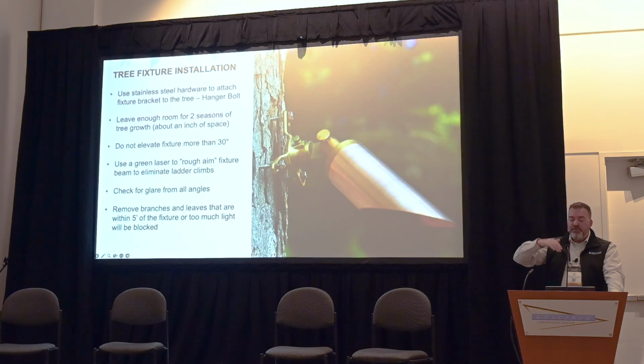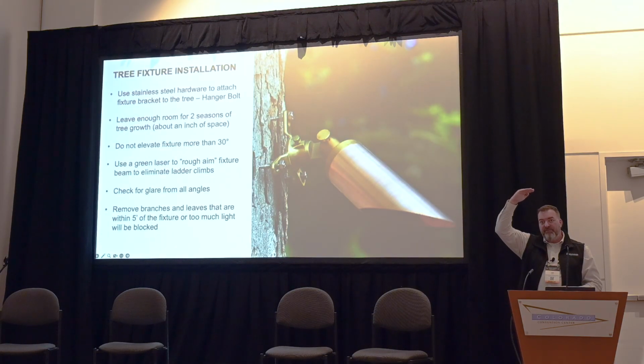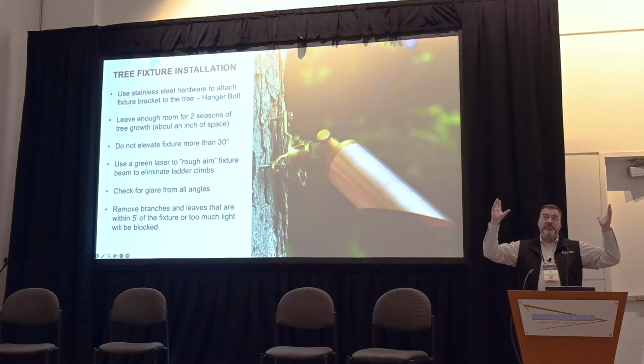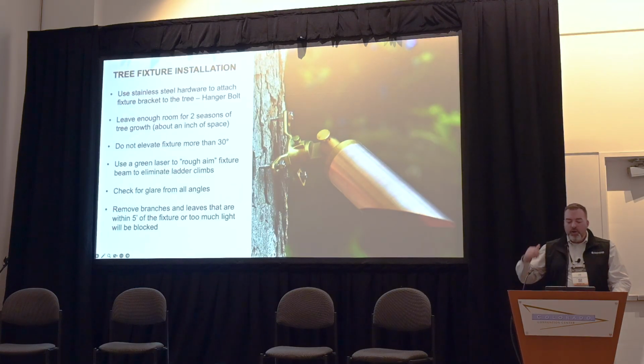But for downlighting, I try to keep it up about 30 feet, because if you look at our peripheral vision for where we see, about 25 feet above our peripheral vision, it kind of fades off. So if you can get that tree light up above that and have good glare control, you're probably not going to see it in most of what you're looking at. Sure, you can look up and see it, but as you're looking across the scene, that's going to be mostly up and out of your vision. So I try to go at least 30 feet or higher for most of your downlights, and then just use optics and your lumen outputs to match it.